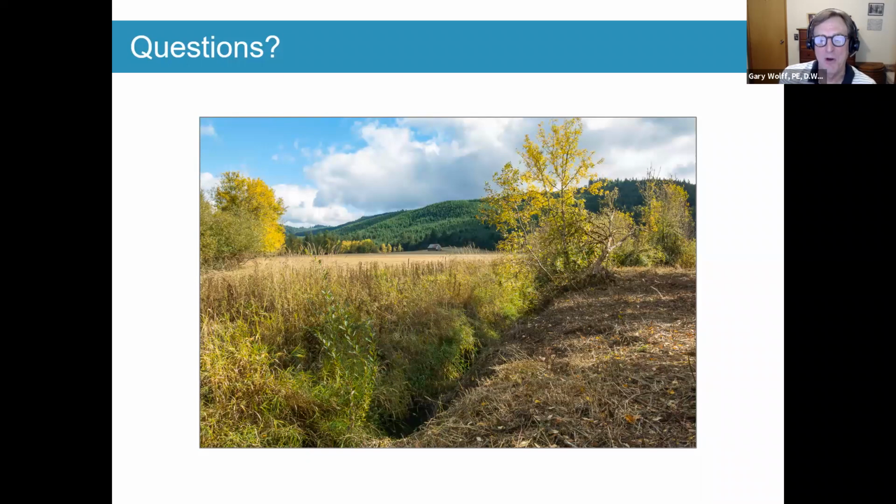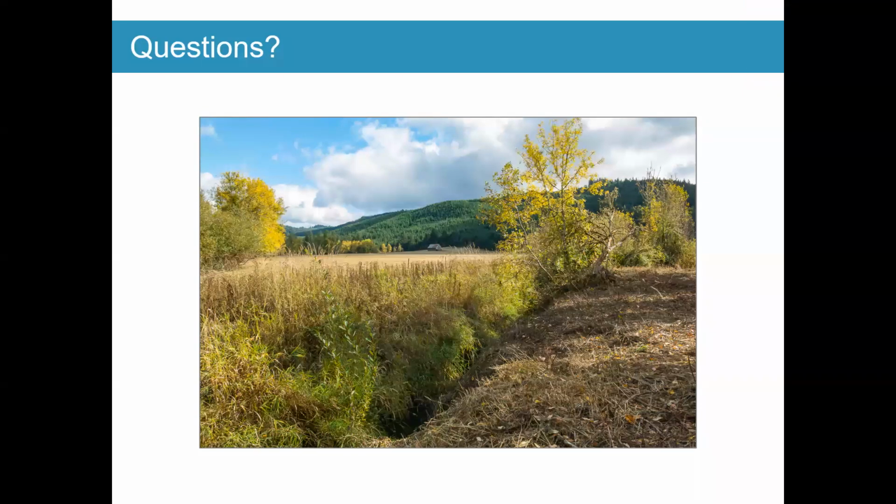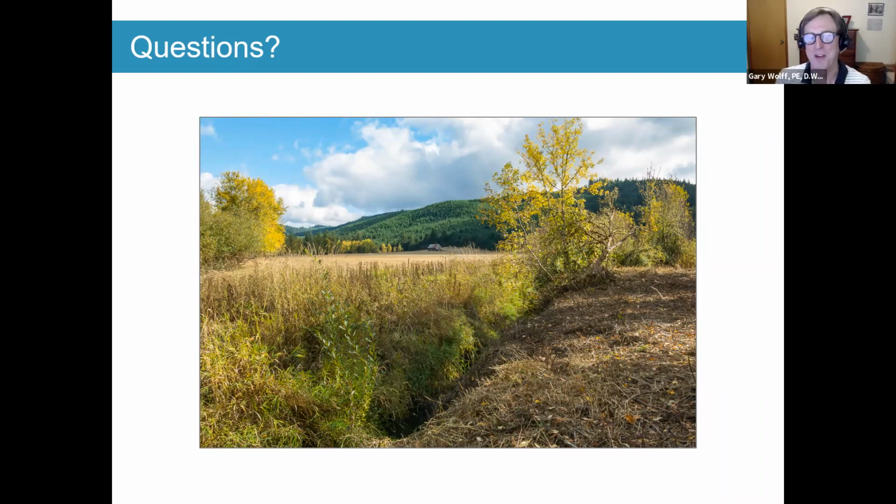I'll just comment really quickly here that the floodplain regulations are trying to catch up with advances in the modeling. The regulations were kind of written in a one-dimensional world where you have one water surface at each cross-section, and that's the no rise. You can't have a rise there. Now with two-dimensional modeling, we're computing a water surface everywhere, and if we had to meet a 0.00 change at every location, we would never get there. I know FEMA is grappling with that right now, and they're trying to come up with ways to maybe calculate an average water surface on a transect or something.